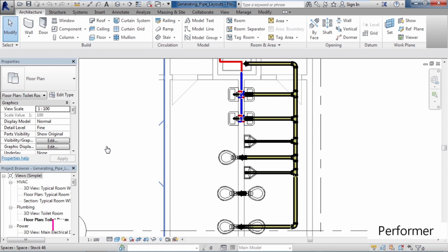We're going to focus on the sanitary lines for this lesson. Typically, your plumbing sanitary lines will have slope. Now, these plumbing systems can be generated in two manners. One, automatically, where you simply select the plumbing fixtures and pipes and points within pipe fittings, and let Revit decide the best route from point to point of how those plumbing lines and segments should be routed.